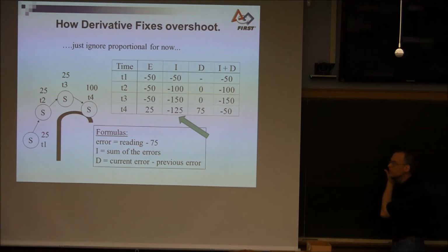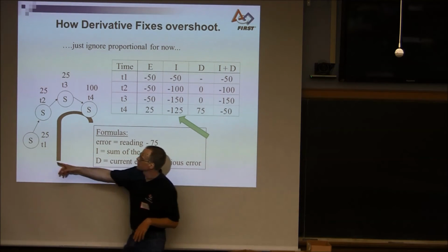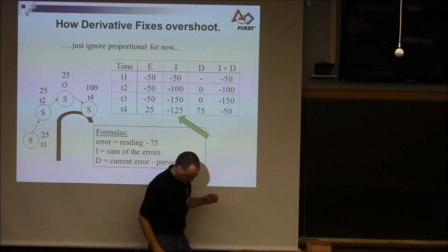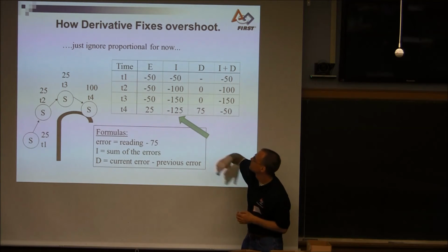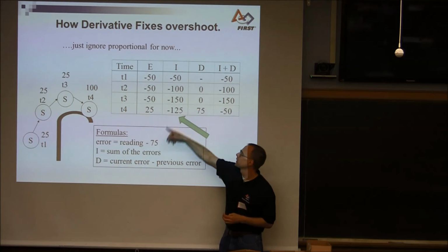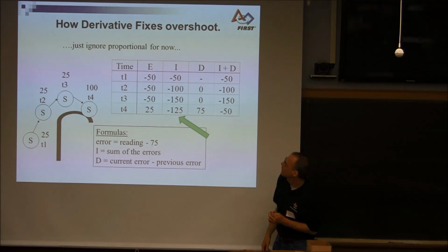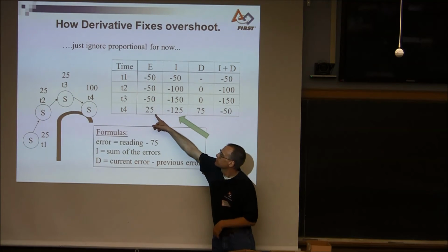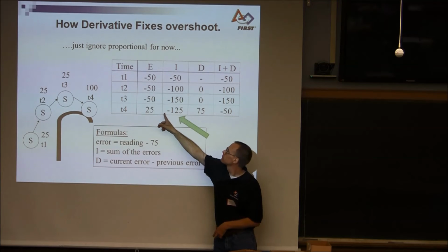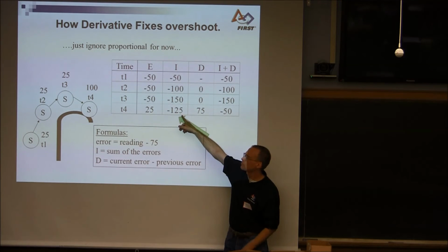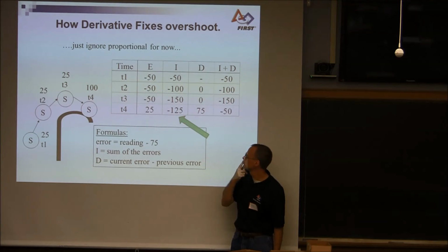So I have a demonstration here, and what I'm trying to show you is, here's my sensor at 4 different times, time 1 to 4, and the number above it is the reading. And you can see, I'm consistently getting the same error. So I'm reading 25 minus 75 is minus 50. Okay. But at time 4, it suddenly snaps back. Now you see my integral grows up, and it's pretty big. And at this point, the error is positive, which tones this down a little bit, but not very much, right? This is still pretty big. I'm probably just relying on that, I'm going to overshoot that line.